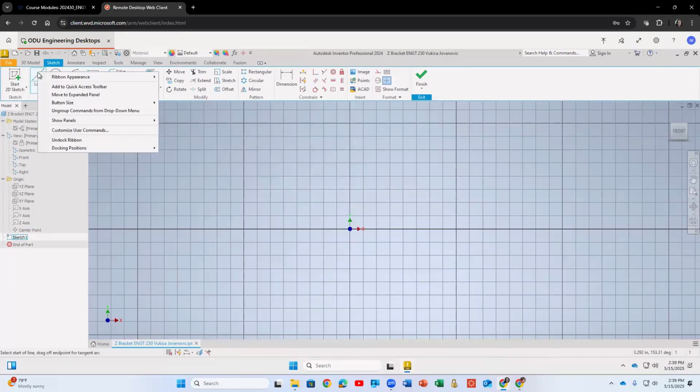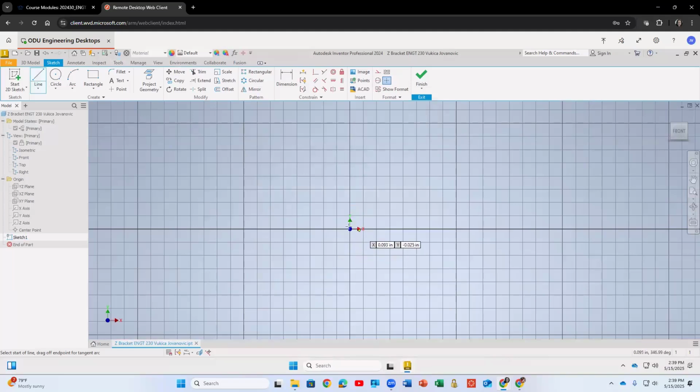You see that one? And I go here and I can go to the left and click anywhere. So you see, when it's purple, it means it's fully constrained, although the left point is not defined. So you see, it's kind of not really in the center, although it looked to me like I did it from the center. It's kind of not there. So, sometimes we need to fully constrain the sketch. So we will add a dimension from the center to the coordinate system indicator, and we will know that the sketch is in the center.